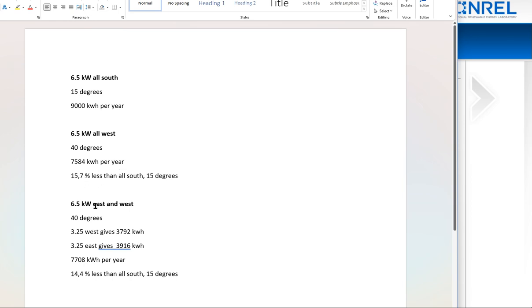So that means that overall, we would have to say that the best solution is to use the existing roof and add a few panels. That's the best solution compared to making a new frame and putting them there. But the key is that you have to add a few panels. So if you're already maximizing out the inverter, then you could have a problem. You can't add those extra panels. So if that's the case, then maybe it's better to go with this one. So that's some food for thought, guys.